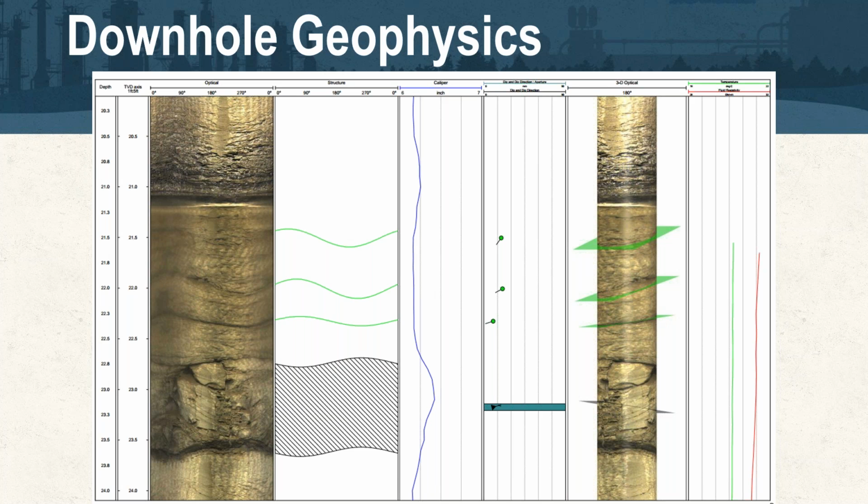In terms of eliminating the number of boreholes installed or minimizing that cost, it can be hard sometimes. The tools we showed you on the earlier slide, the Westbay, the Waterloo, the FLUTe liners, the Solinst systems, those can sometimes help with that. If those can be retracted from the borehole, that borehole can be used for injection, and those can be reinstalled. So that gives you a borehole that wouldn't need a sister borehole adjacent to it for monitoring. They can be continuously reused.